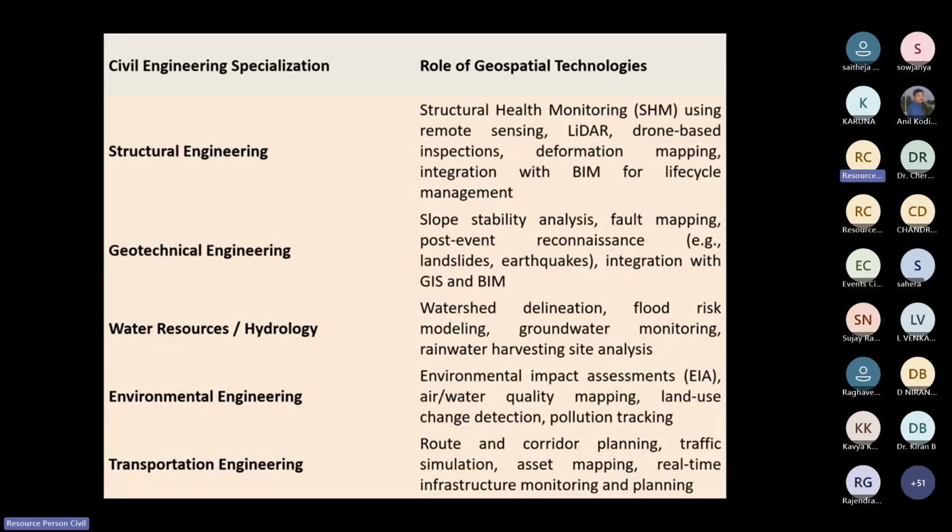Then you locate where you are collecting and what the traffic volume is at different locations spatially. Once you collect that data, you integrate it into GIS form, and then you can analyze several things. What diversions can you suggest? What road expansions can you suggest based on those analyses? These are very useful pieces of information for us.